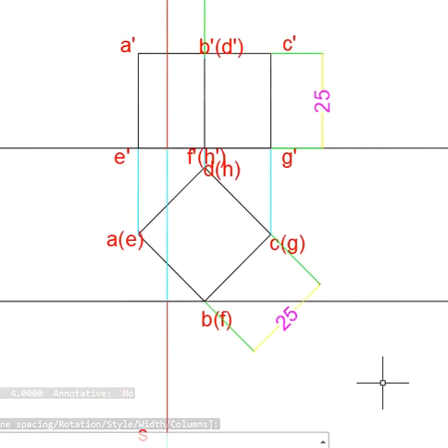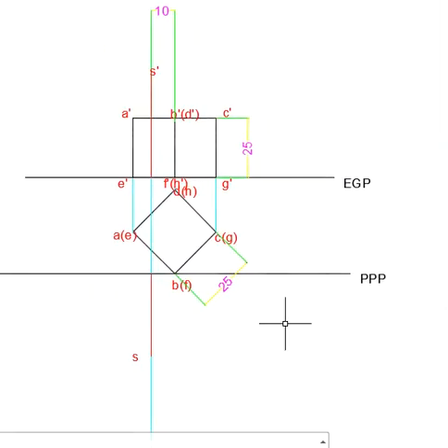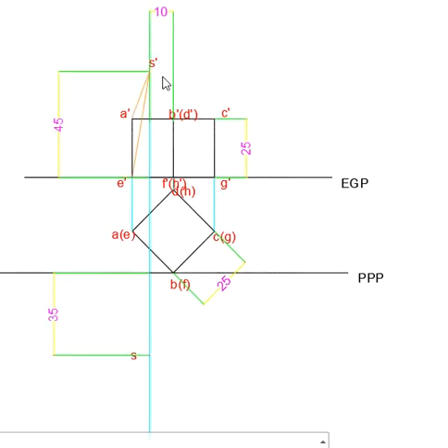So these are the points. Now you can draw visual rays connecting this point and all the corner points of the cube. So you have to draw 8 visual rays in front view and 8 visual rays in top view. Now draw the visual rays in front view like this. From S dash we are drawing lines to all the corner points. Total 8 points are there, but 6 points are visible in front view. We are drawing 6 visual rays like this.